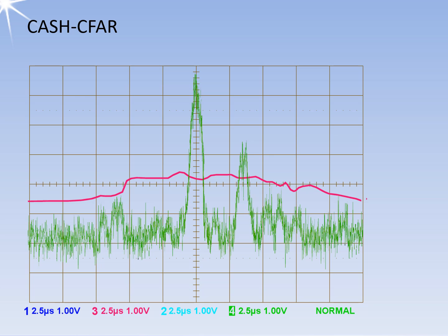Two neighboring target signs can no longer mask each other. Their temporal side lobes from the pulse compression are reliably suppressed by the threshold. With this method, the time-critical sorting can be dispensed with, so that the computational effort is significantly reduced.